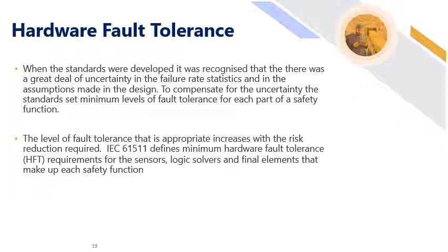The reason for this was that it was identified early on in the development of the standards that there was some uncertainty in failure rate statistics, and to compensate for that with higher levels of SIL, they added this requirement. So as the SIL levels go up, then the requirements for the hardware fault tolerance get a little bit more strict.